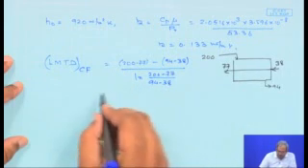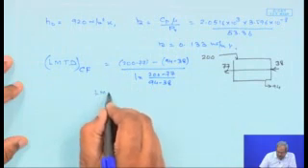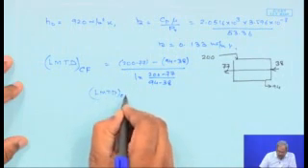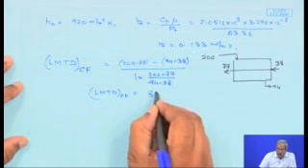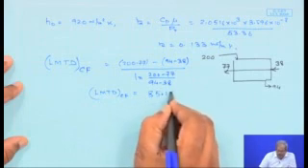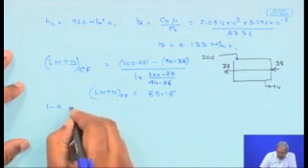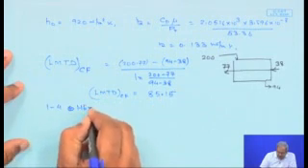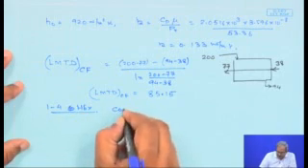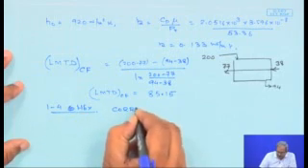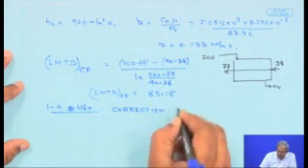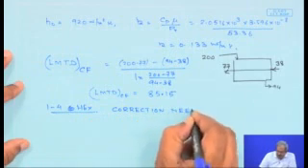So, once you calculate that, this LMTD based on counter flow would turn out to be 85.15 degree centigrade, and since it is a 1-4 heat exchanger, a correction is needed for LMTD.